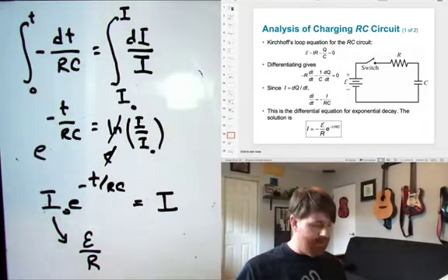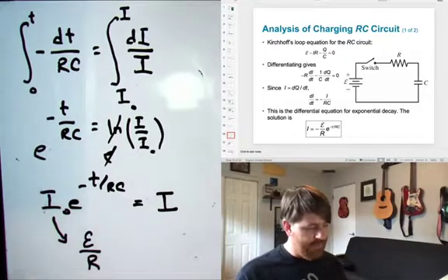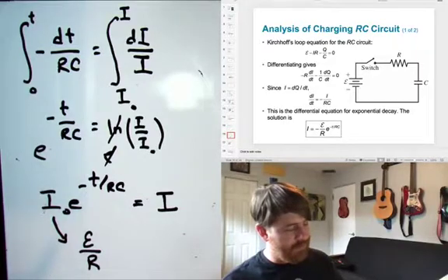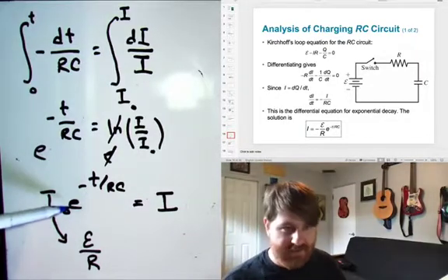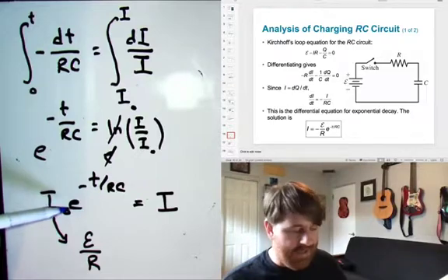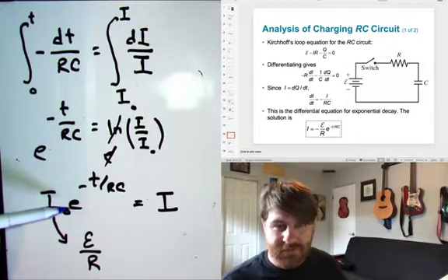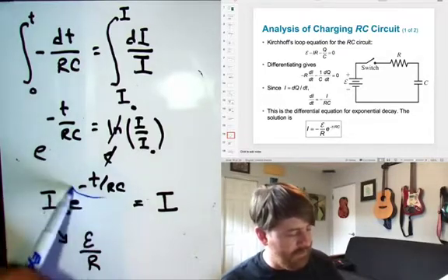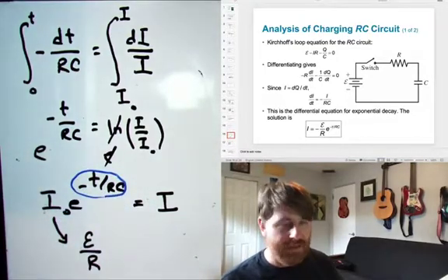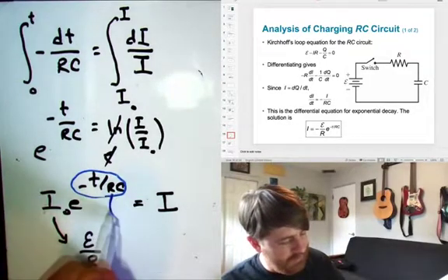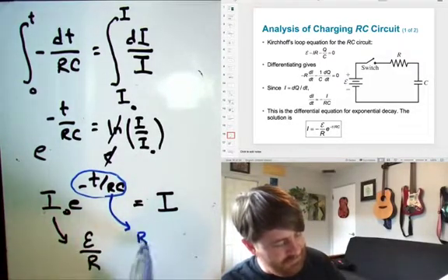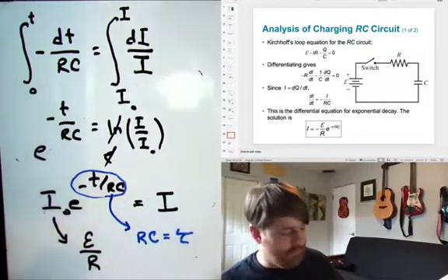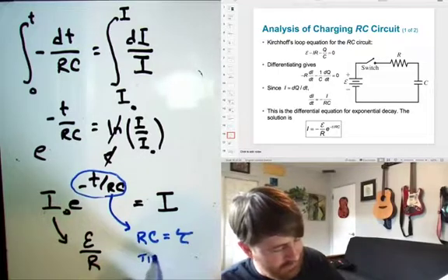Right, so when we have exponential functions like this, we have to recognize that it wouldn't make any sense to have some units like e to the minus coulombs, right? I've never heard of anything like that. So that means that the expression that we're exponentiating must be unitless. And this thing down here, which is just the resistance times the capacitance, we often label tau, and that's what we call the time constant.